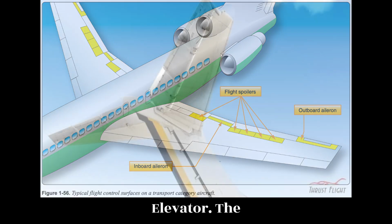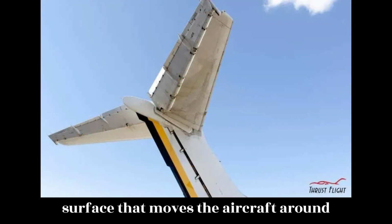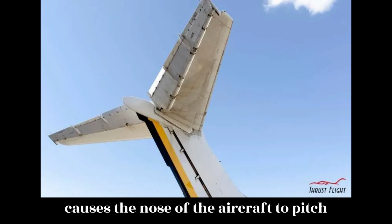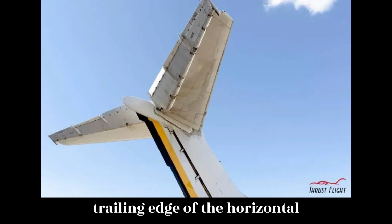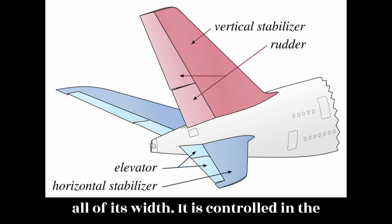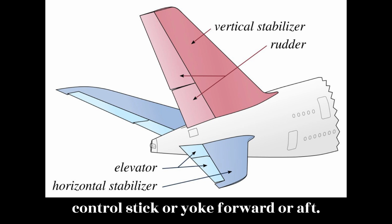Elevator. The elevator is the primary flight control surface that moves the aircraft around the horizontal or lateral axis. This causes the nose of the aircraft to pitch up or down. The elevator is hinged to the trailing edge of the horizontal stabilizer and typically spans most or all of its width. It is controlled in the flight deck by pushing or pulling the control stick or yoke forward or aft.